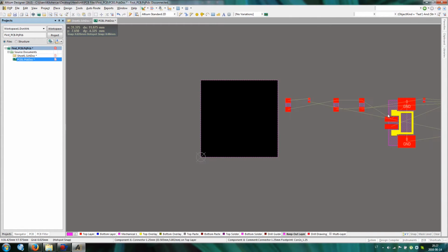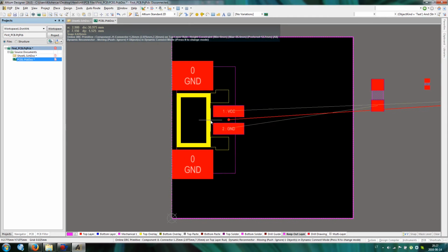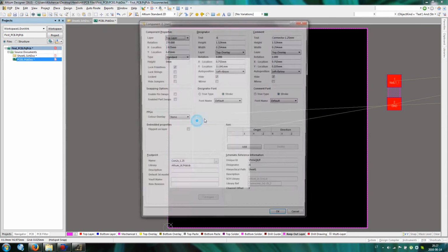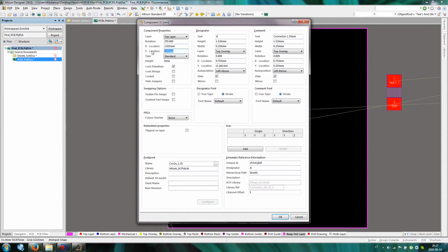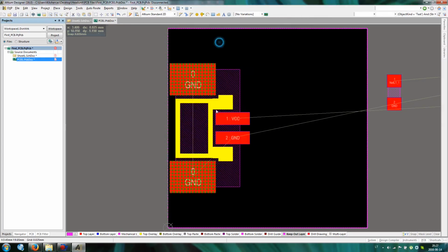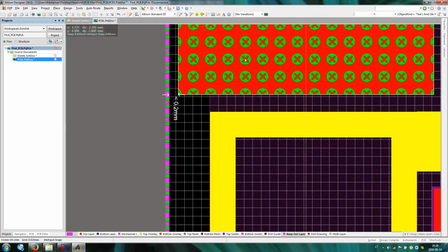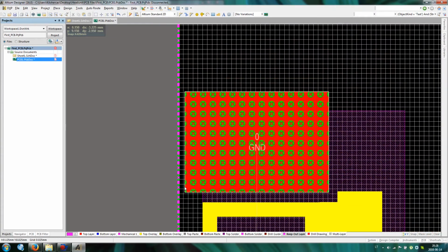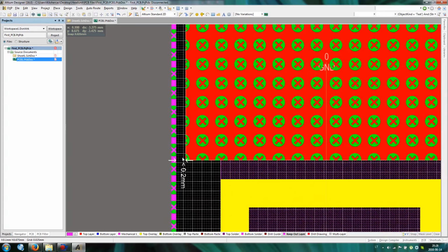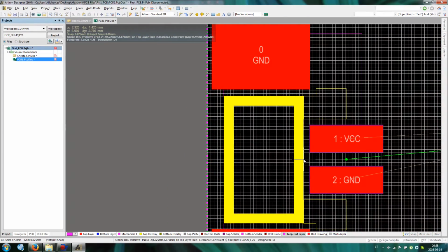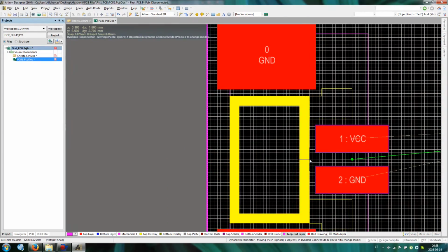Okay, so let's just make the PCB. It was 6.5, it will be in the middle. Now, what is this? Basically, if we have these cross marks, it means something is too close. So our part is too close to the board edge. So let's just back it up.